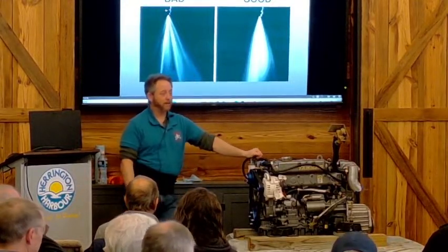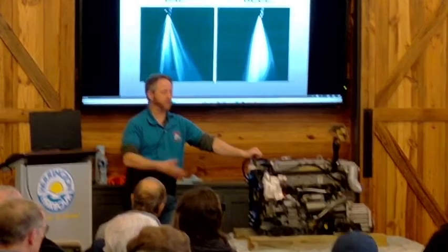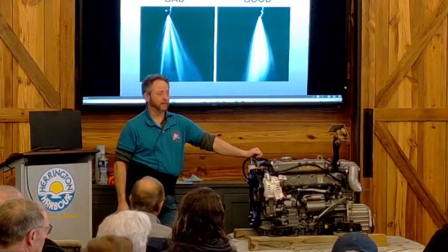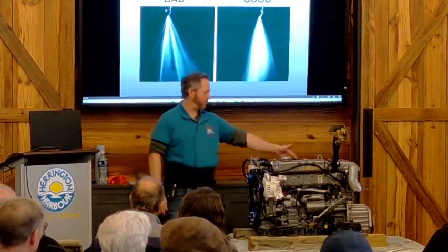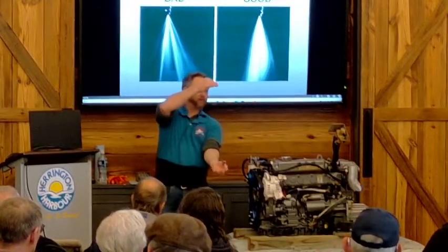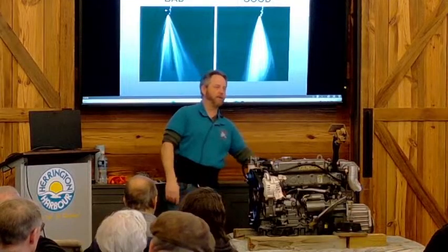So you're pulling it out through a tube then? Yes. Going down to the bottom of it? Yes. I see. Yeah, some engines don't have a pump out, so that's the only way to do it. I thought you were pulling a vacuum from the top. On this engine, yes, the dipstick tube itself is a pump out, because they design it to go right to the back corner of the oil pan.